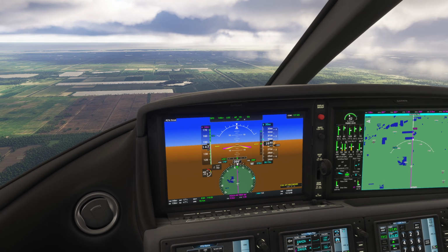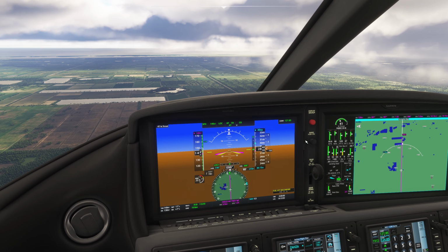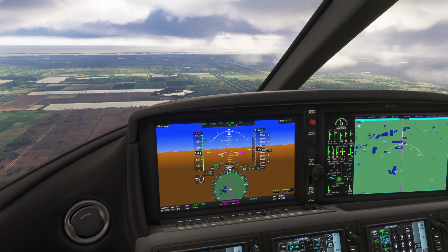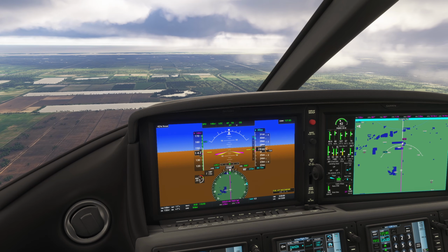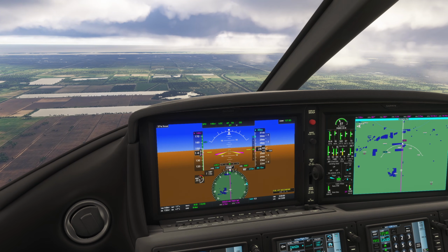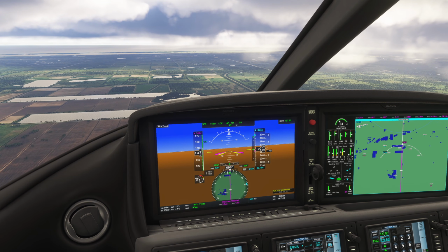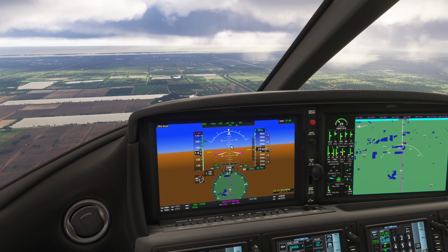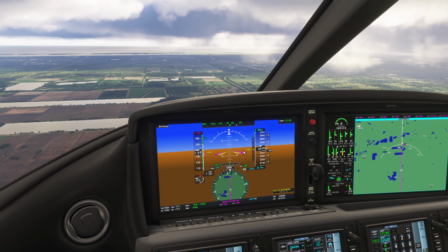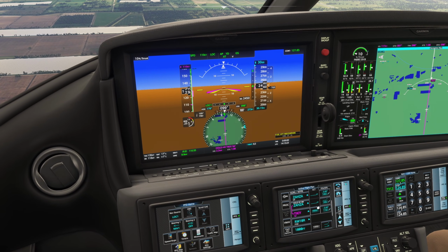And now the speed should change when we get to Tiki. That's where we're going to put our gear down. As this plane does not have speed brakes, we can use our gear to slow us down. And that VLO, landing gear operating speed, is 210 knots. So if we're below 210 knots and we really need to slow the aircraft down, we can put the gear down. So the plane is now targeting 110 as we have set here, 110 knots.